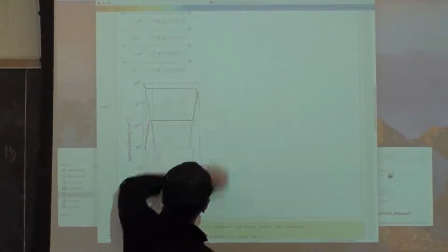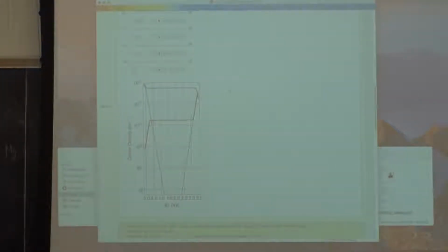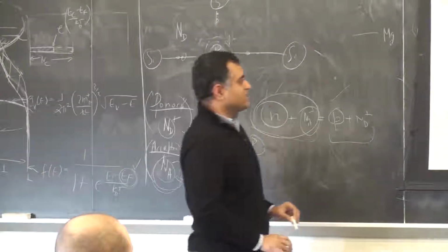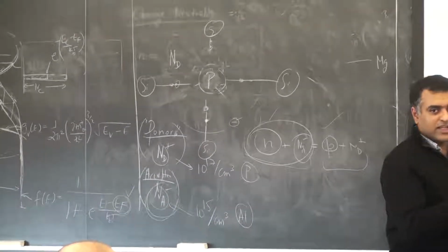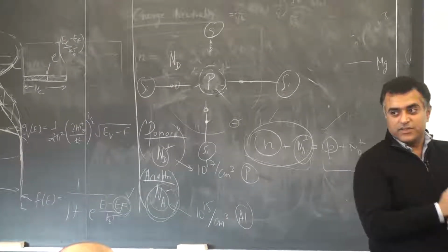Similarly, the blue is the total positive charge. Right? I'm just kind of plotting all the parts of this equation. So maybe you can tell me where's the Fermi level now, right? It's when the total negative and the total positive charge meet. That's where the Fermi level is. Therefore, in this picture, it's right here.